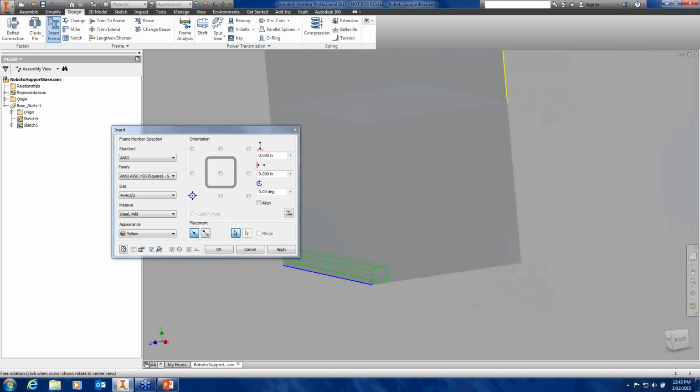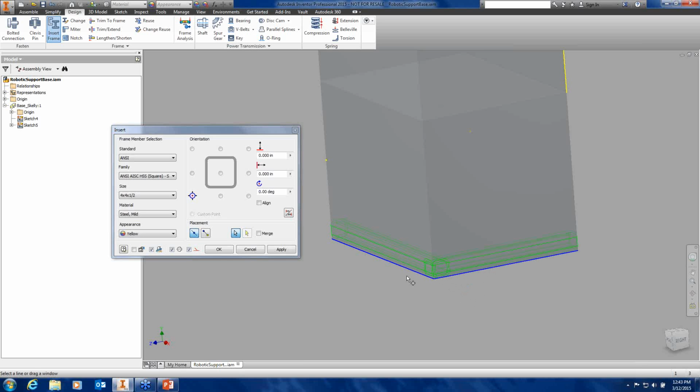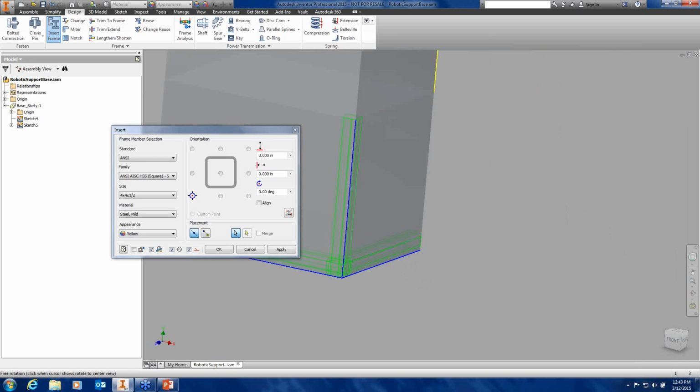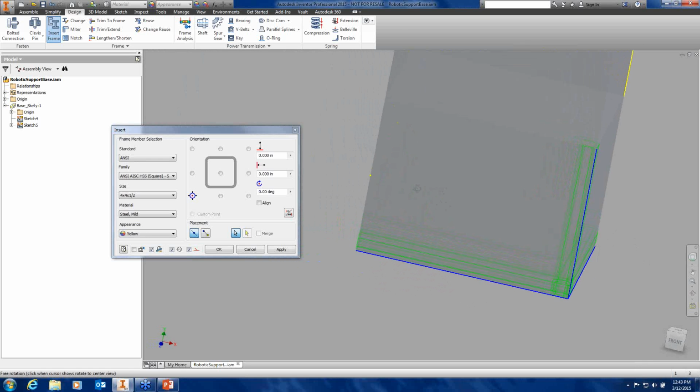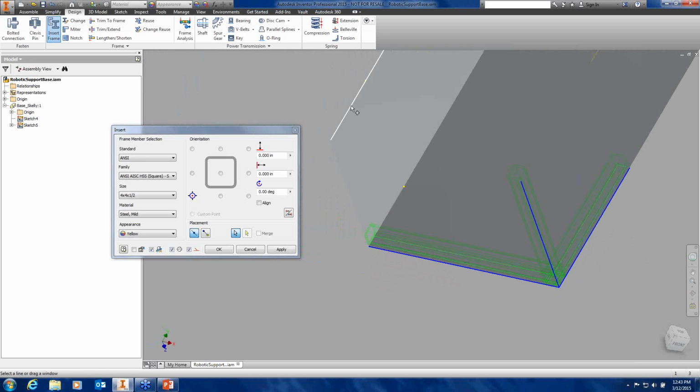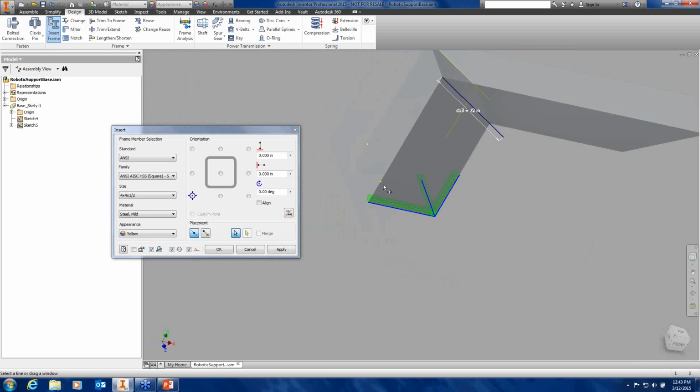Now, here is the trick when you go to place these things: if you pick an associated point to the line that you just did, it will understand that you want it to stay in that justification. If I'd have gone out, for instance, right now and over here to this backside and picked that point, there's a good chance it won't come up inside of the box. It could very well be outside of the box.